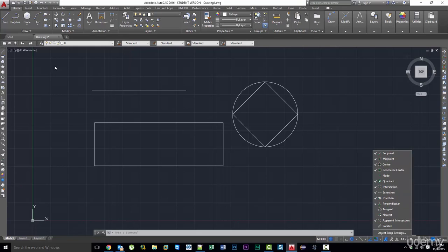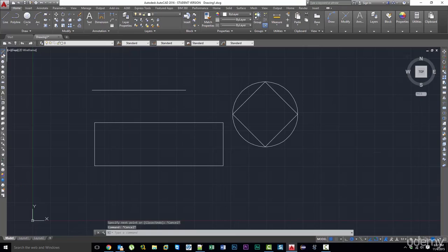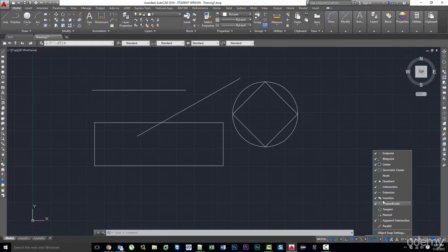This is another cool one. Let's say that I went ahead and drew a line somewhere across this rectangle, but for whatever reason, where that line crosses that rectangle is pretty important. No problem. I've got a snap point there, shown by an X. It hovers and says intersection, and I can work straight from that intersection where those 2 lines meet. So again, another awesome snap point that we will make use of.